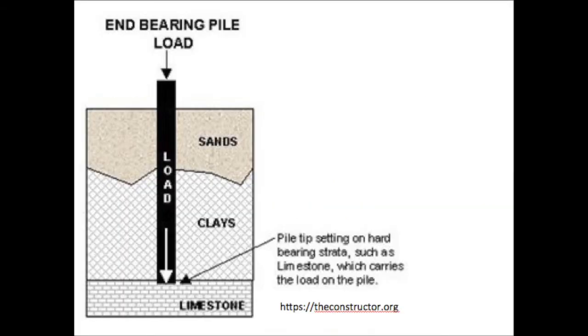As shown in the introduction, the most used deep foundation design for mitigation of liquefaction-induced damage is end-bearing piles. End-bearing piles are used to transfer the load from the superstructure down to a layer of soil that is strong enough to hold the required load from the superstructure.